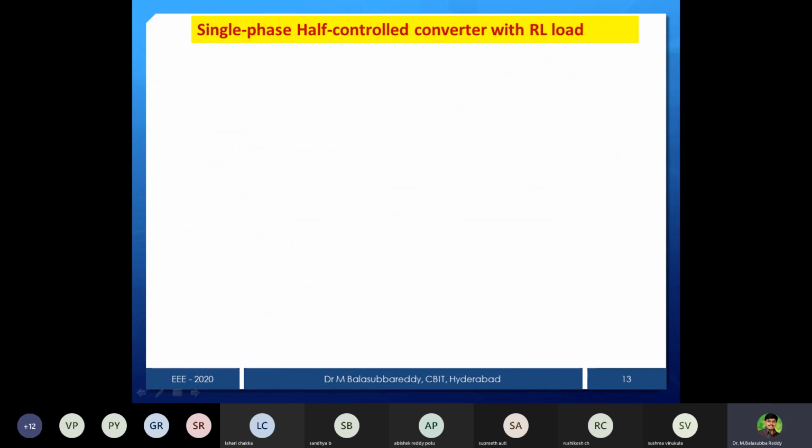And now from later on, whatever we used for the loads, other loads also, formulas will not change. Only change will be integration limits, where it will start and where it will end for the conduction. Once we clear that, only substitution is VDC expression, VRMS expression. The remaining all formulas are the same.